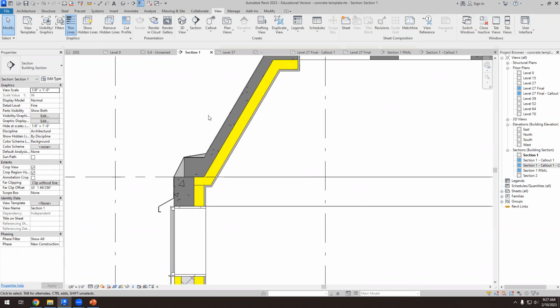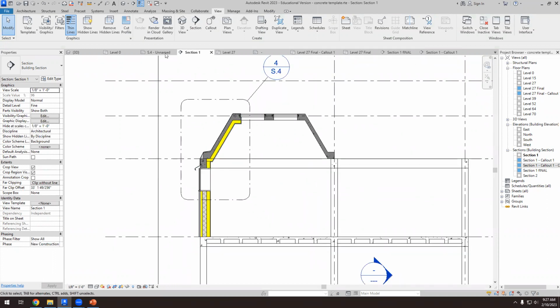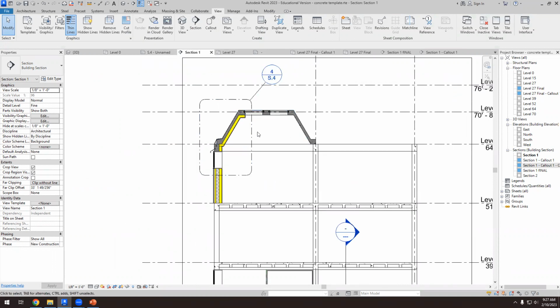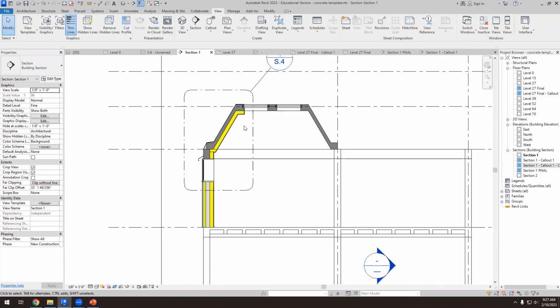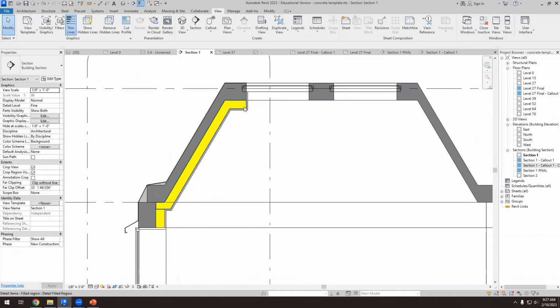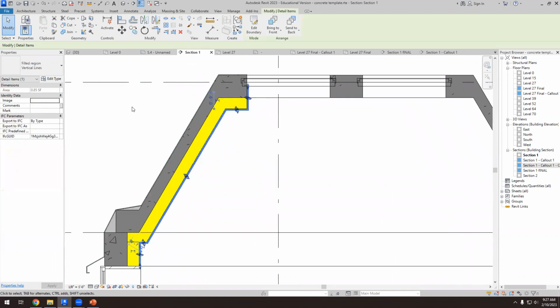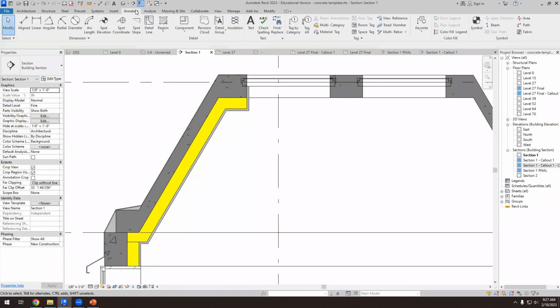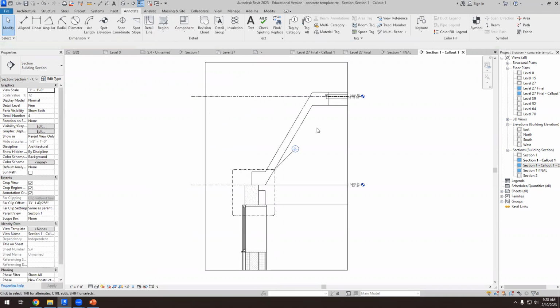So that's another lesson that you have to learn. Don't work on the same section. First, we need to understand what we want to do, and then we have to apply different levels of detail to different drawings. Because if I'm working with a 2D, I use this annotate detail regions, whatever. Those regions only show up in the drawing I'm working. So if I zoom in and I create a call out, then it doesn't work. I have to do it again.